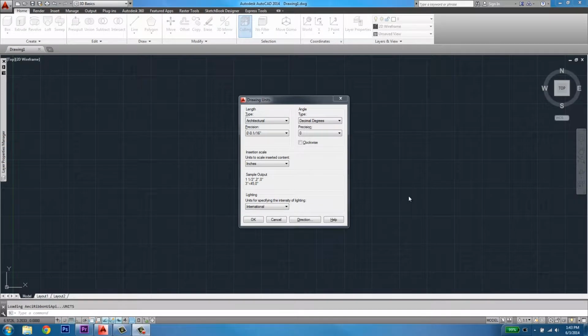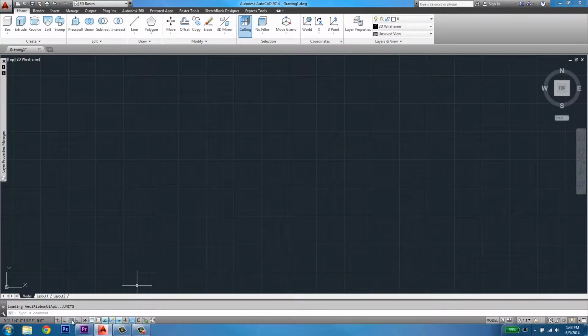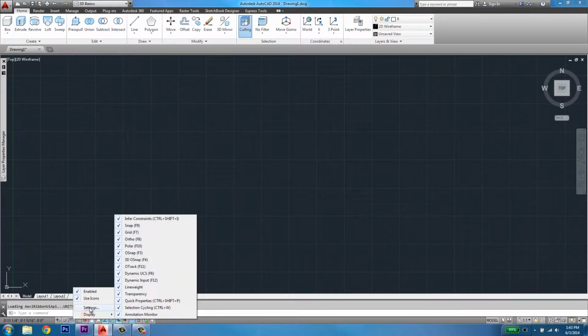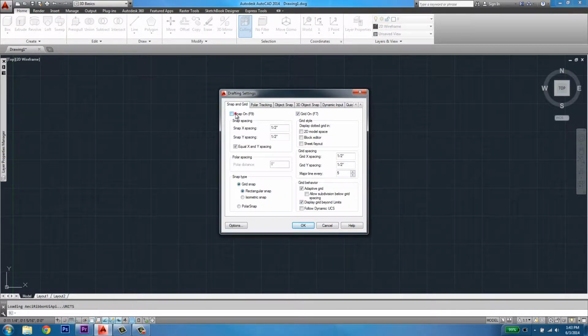Drawing 3 begins a lot like Drawing 1. Remember to have your units set in architectural inches. I found that it could save time if you're doing several drawings in a row if you set up your grids, units, and layers in a blank drawing, save it as a blank drawing, and then just open that one each time and save it as whatever drawing you're on. That way you don't have to set it up each time.